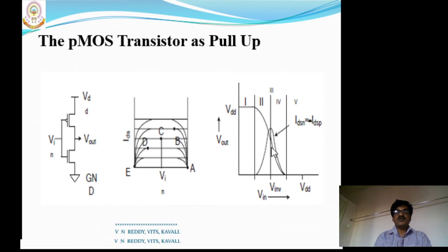Why? Because one transistor goes from on to off, whereas the other goes from off to on. That's why there is an instant when both transistors are in on state. There a short circuit will occur between VDD and ground, so we can observe short-circuit current flow. The resultant power dissipation is short-circuit power dissipation, but it occurs only for a very finite time.